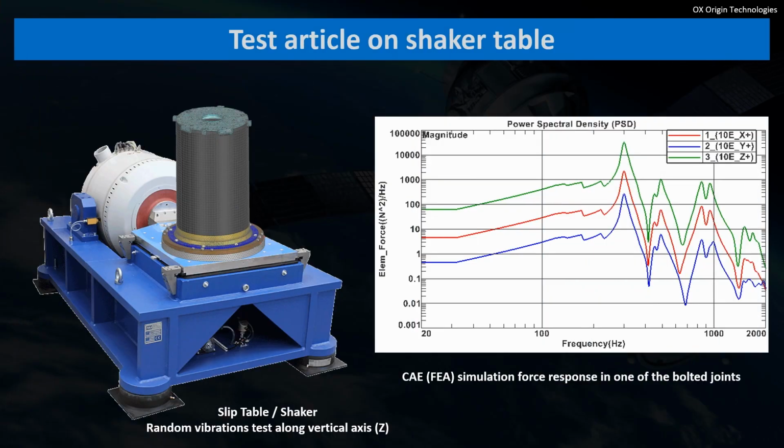The vibrations generated by the shaker table induce forces or loads into the bolts that keep the optical payload together. Therefore, the bolted joints of such a mechanical system must be sized correctly and verified in advance in accordance with industry standards such as ECSS and VDI to ensure the system will survive such a physical test.